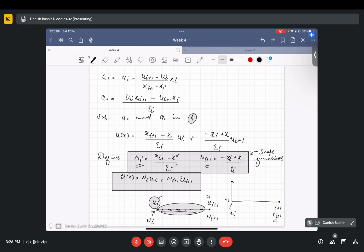Since x is linear in the shape function itself, it will be linearly decreasing like this. At this node it has value 1, and at the other node it has value 0. So it shows how this nodal value ui is going to contribute to the other part of the solution, at other points.